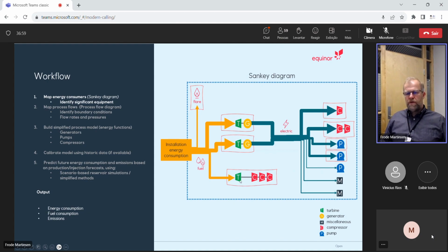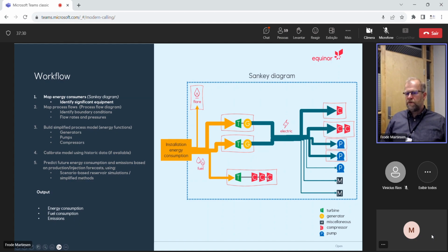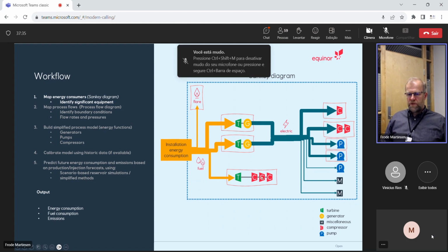And also down here, you'll have a turbine with a shaft that runs compressors directly. Over here, you have a turbine driving a generator that drives a compressor train, and these have electric motors, which is not drawn here. But here, this is a more common situation for large compressors. You have a turbine with compressors mounted directly on its shaft. Instead of a G, you have C. In this case, you have 3 compressor stages on the same shaft, meaning that there are 3 compressor stages which rotate at the same speed.